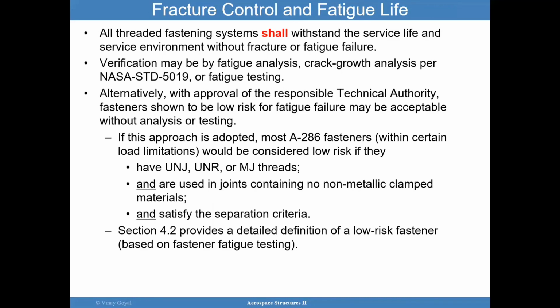There is a whole area of fracture control and fatigue. All fastening systems have to meet the service life definition without fatiguing and fracturing. One can typically verify these specs of fatigue and fracture against NASA 1519 or some fatigue testing. But there are approaches that allow you to consider it to be low risk.